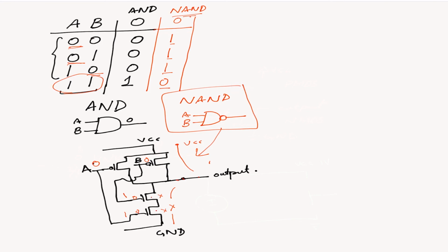Somebody asks, how many NAND gates do you have? We roughly model it that a NAND has about 4 transistors, so how many cells or gates do we have in the design? So the NAND gate is used as a measuring entity for size as well as area count.